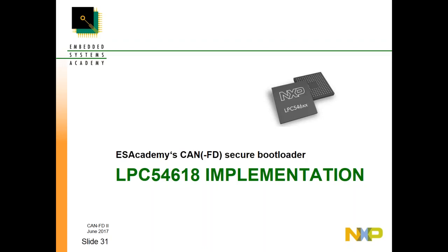So really, if you would want to enforce a downgrade, you generate a version of the old code where only the firmware version number is higher again. But then, of course, this is a workaround which we actually want to protect you from. But I understand that sometimes you have to get your systems working again. It's an option. We can disable it, but keep it in mind, as I said, this is the first thing attackers will try to do if they have access to older firmware versions: see if they can downgrade the device before they launch other attacks.